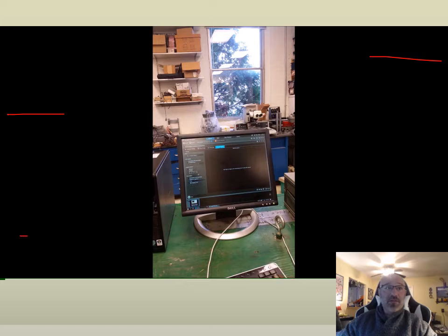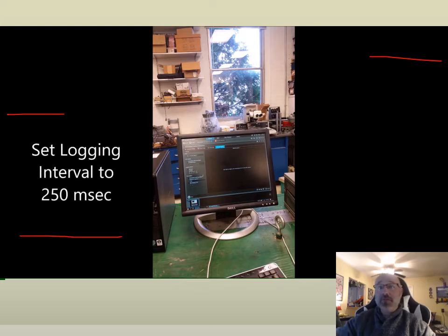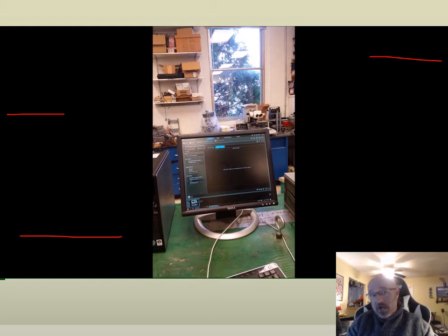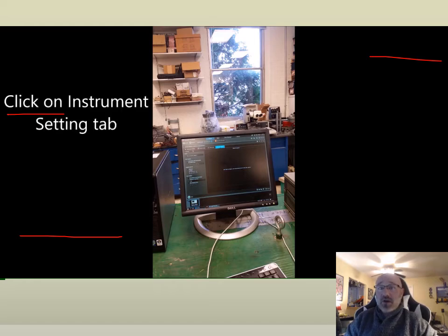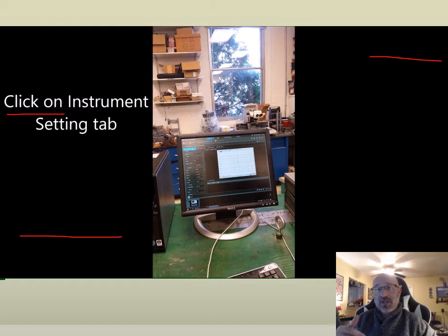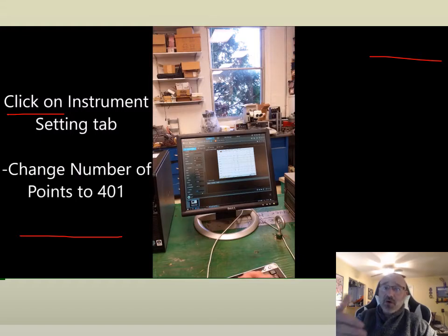So right here now we're setting our number of captures, so that'll be how many steps we move forward with our linear drive. So 250 steps over approximately 1 meter of the length of our sandbox there. So this is where it'll move forward, send out a signal, receive the signal, save the data, then move forward again 250 times.